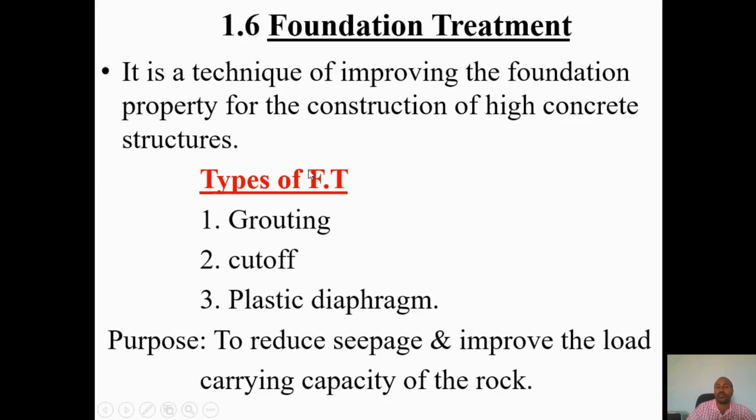So the main purpose of foundation treatment is to reduce what? Seepage and improve the load carrying capacity of the rock. So once you fill the void spaces with these techniques, with this foundation treatment, either grouting or cut-off or plastic diaphragm, you can reduce the leakage or seepage, just flow of water under the subsurface, and also you can improve the load carrying capacity of the rock. So since you just fill the void spaces, then you can improve load carrying capacity of the rock.